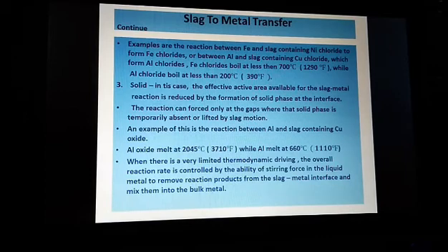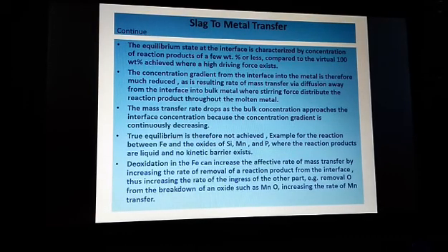When there is a very limited thermodynamic driving force, the overall reaction rate is controlled by the ability of stirring force in the liquid metal to remove reaction product from the slag metal interface and mix it into the bulk metal. The equilibrium state at the interface is characterized by a concentration of reaction product of a few percent or less, compared to the virtual 100% weight achieved where a high driving force exists.